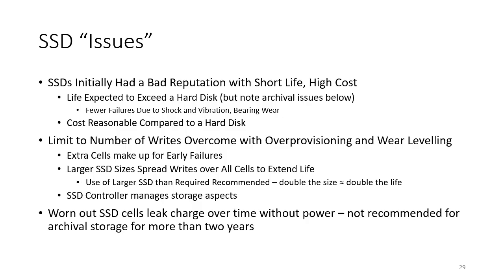But the problem with the SSD memory is the cells do leak that charge, and if an SSD isn't powered up for a long time, they can eventually lose their states. So my recommendation is, if you want long-term archival storage, you wouldn't use an SSD for that. An SSD will store data for up to about 2 years without power, but after that it might lose data.